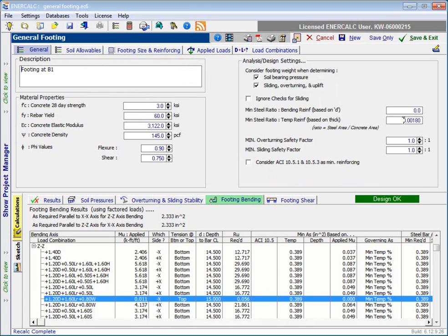What we provided was the 0.0018 value that's common for footings. And the way that the module is currently implemented, it calculates that 0.0018 value and it requires that in this column here, and it doesn't actually take into consideration whether there is a top mat or not. So what ends up happening is that in the current implementation, any mat will be held to this entire value.